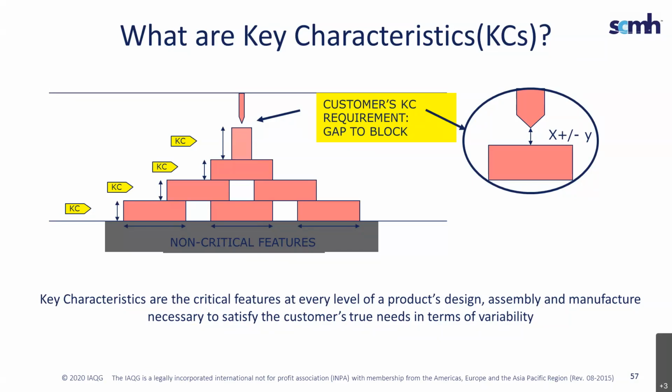And what you want here, why this would be a key characteristic, is this has become an attribute over time of being some indication of quality or variation control in the product. So when you look at a car or a plane and you see inconsistent gaps between the doors and the windows, where one gap is large and the other gap is small, or a gap converges, starts out large and becomes small, this tends to become an assumption of poor workmanship or poor quality. So this has become a key characteristic, that these gaps maintain consistency.